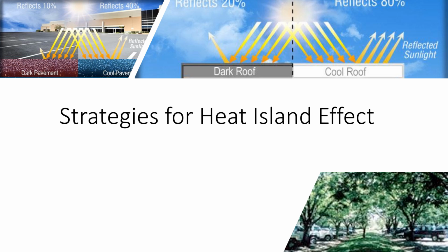A steep-sloped roof must have an initial SRI of 39, and with a 3-year aged SRI of 32. Or you can use a vegetated roof, or use renewable energy systems such as photovoltaic, solar thermal, or wind turbines.